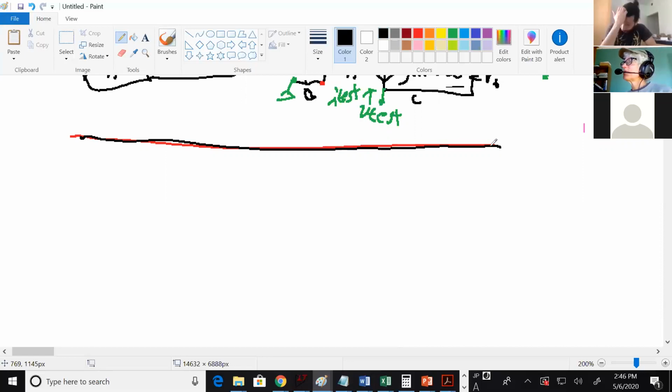Here's a challenge for you. Today you saw we were working with single transistor amplifiers up to now and finding the R ins and R outs and gains. And then I just threw a single transistor at you and said, assume this is an amplifier, now what's the R out? Any circuit that comes at you, if somebody asks for the R out, it's the same process. You replace the transistors with the small signal models and then put a V test and an I test on it and see what resistance you get. So I'm going to give you a random circuit. It's not an amplifier.